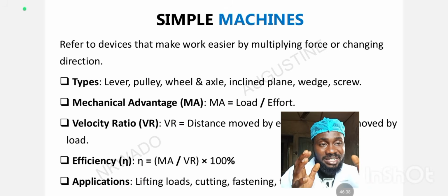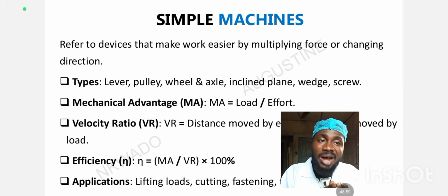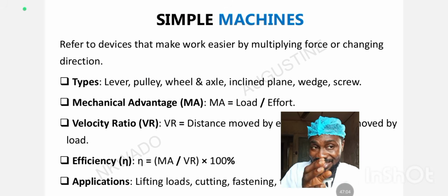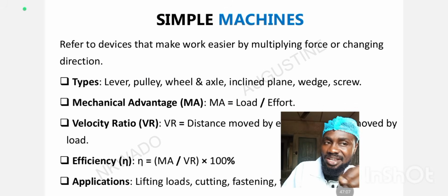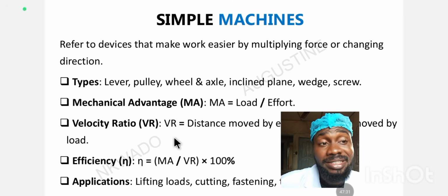In the first class lever, you have the fulcrum in between the effort and the load. In the second class lever, you have the load in between the effort and the fulcrum. So you can see the difference. The fulcrum shifts, so know the position of the fulcrum in each of the levers, so you can define them and know their examples.